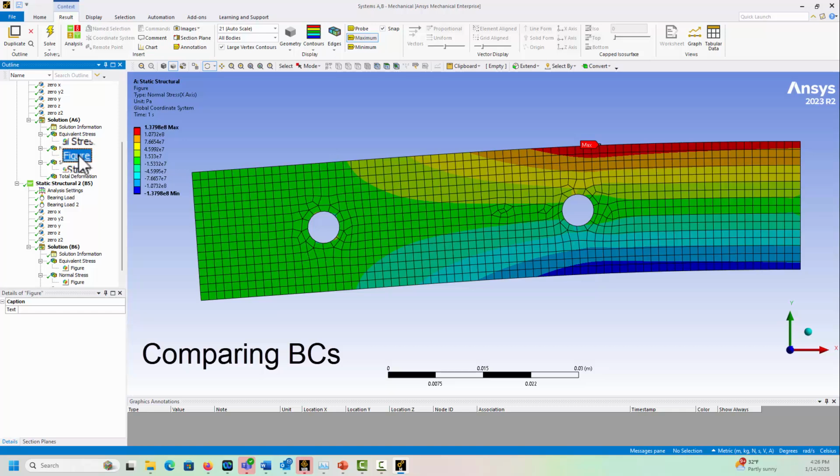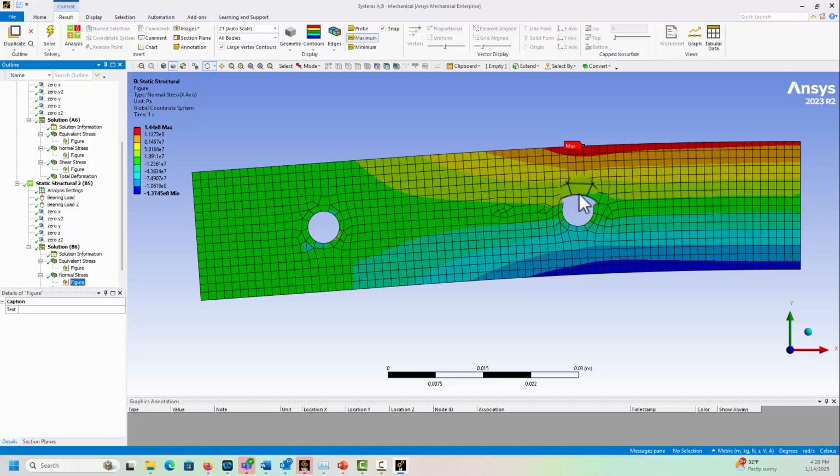Now, that probably makes sense because if you think of the path of the stress in here, if it's pushing up on here, the stress is kind of coming up and around. So there's going to be some extra stress at the top of the bar. And there's essentially some stress concentration effects that are happening from that hole in that region.